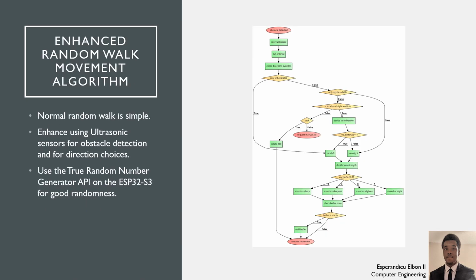As described earlier, the simple random walk method does surprisingly well at covering a space. It does very poorly, however, at avoiding obstacles. To combat this, the random walk implemented in the Sentry will use the included presence sensors for obstacle detection on top of the human presence detection. In this way, a virtual barrier is placed around the Sentry, not letting it hit anything immediately around it.